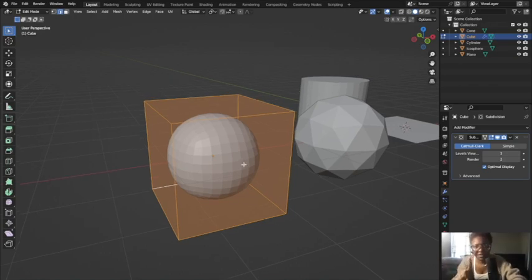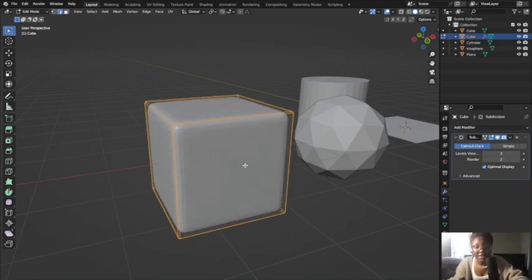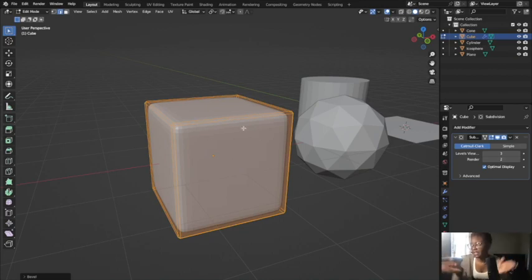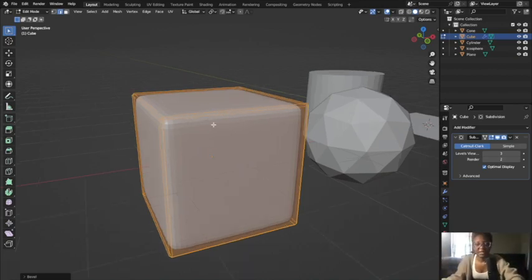So remember how to bevel a mesh. We're going to press Command B on a MacBook, and that's going to allow us to create a couple of bevels in here, right? And now you can see the benefit of using this tool. This is what really makes it cool. And we can add segments in the bevels to tighten up those edges a little bit, and that's just going to allow us to create some softer edges around the mesh. All right, so that's what the subdivision modifier does.